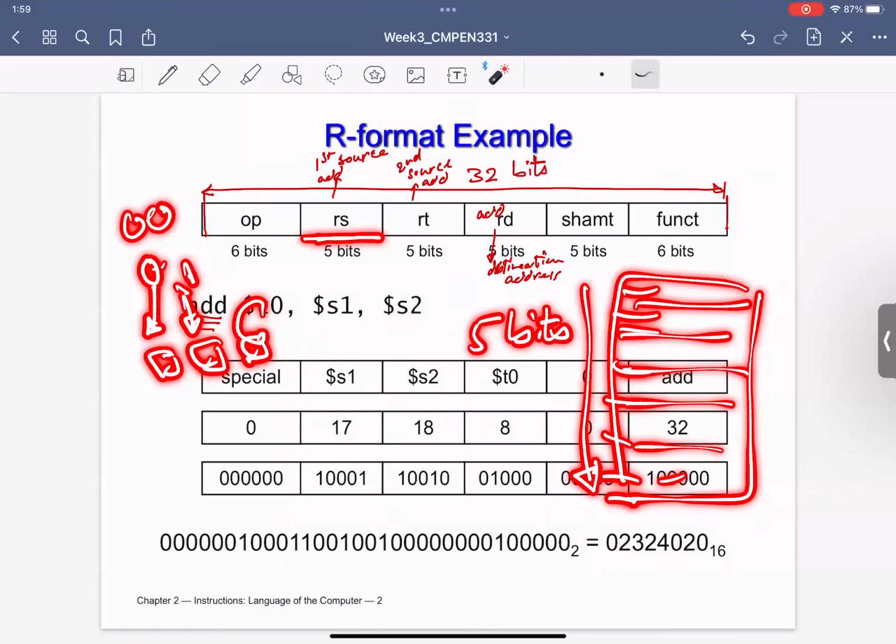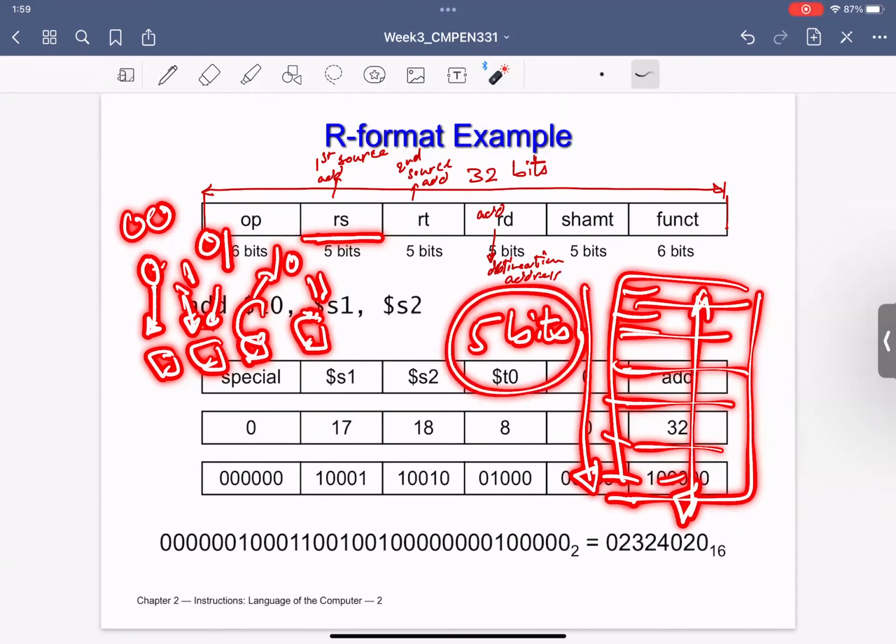So this will be 0, 0 as an example. The other one will be 0, 1, and maybe this 1, 0, and the 1, 1 will not be used. Or if we have a fourth one, then I can use the 1, 1, and so on and so forth. Here I have 32 of these, so 5 bits will be enough to address any of the 32 locations.